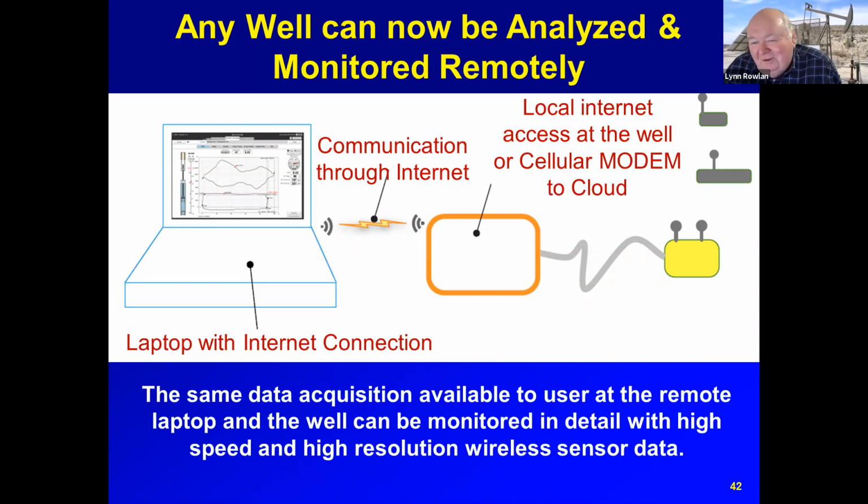When you shoot it, if you put too much pressure in your gas gun, you just want to use a little bit of pressure over the well pressure, so you don't put a bunch of energy in the well when it has a really high fluid level. Then when you shoot it, if you have, let's say, 100 pounds of pressure, that echo just bounces back and forth really, really fast, and it gradually dies out. It looks really big at the beginning of the shot, and it looks like a funnel, or a tornado. It just goes from big to small as time goes by.